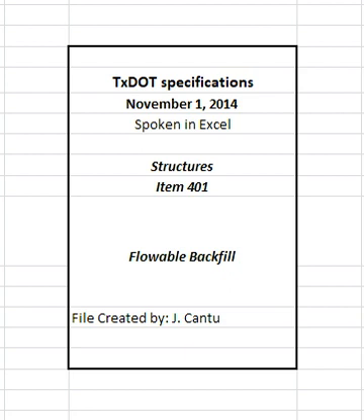Use materials from non-listed sources only when tested and approved before use. Allow 30 calendar days for the engineer to sample, test, and report results for non-listed sources. Do not combine approved material with unapproved material.